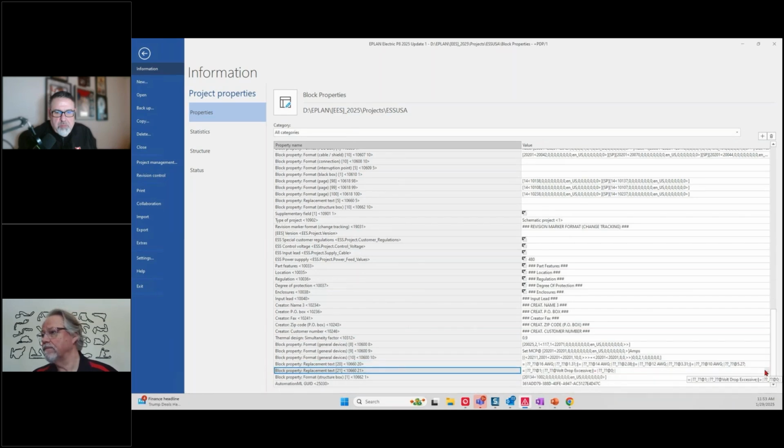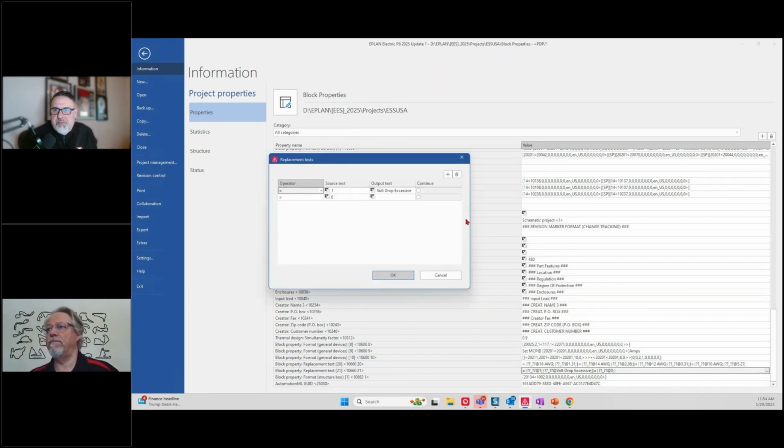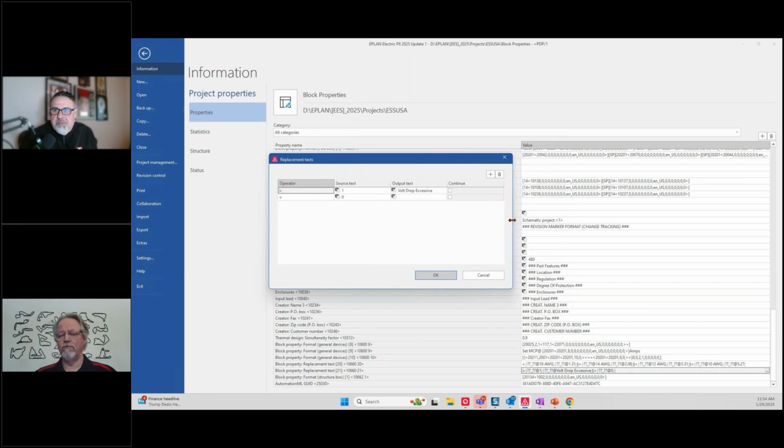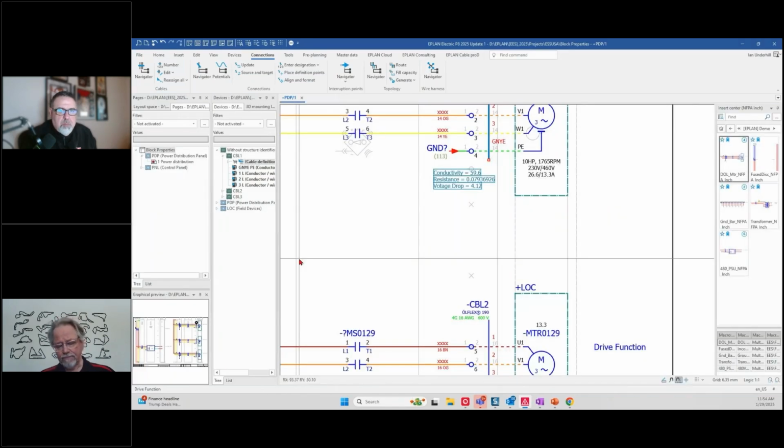That one. So what I did was, if the value is 1, I did the comparison looking at whether the value was greater than the 3% that I calculated, then I said the volt drop is going to be excessive, and that's going to display. If it's less than, don't display anything. So that's the way I highlighted an error by using the value.